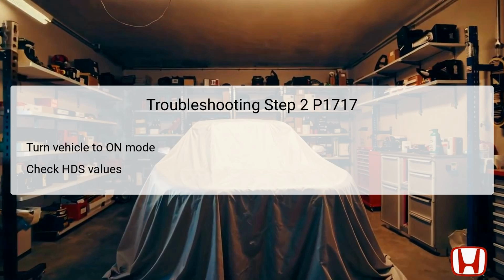The next step involves turning the vehicle to the on mode and utilizing the Honda Diagnostic System, HDS, to monitor values pertinent to the ATR switch and reverse switch, ATP RVS. This step is critical as it identifies whether the current status of these switches indicates an issue. Once in the on mode, shift the transmission to the reverse position. If the HDS displays that the ATR switch or reverse switch, ATP RVS, value is off, the failure replicates the condition that triggered the DTC.